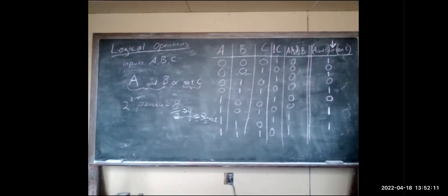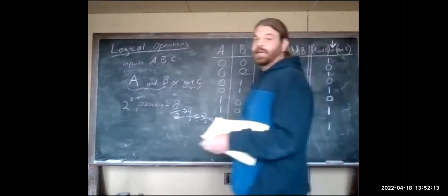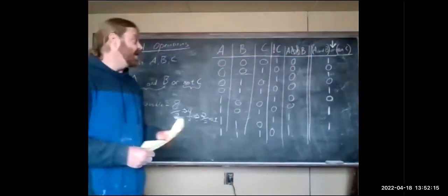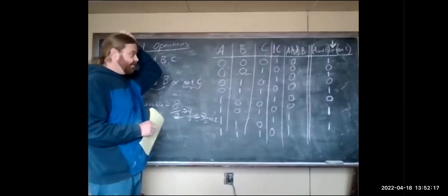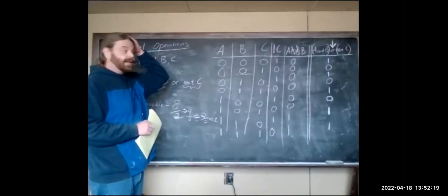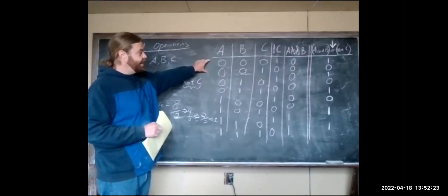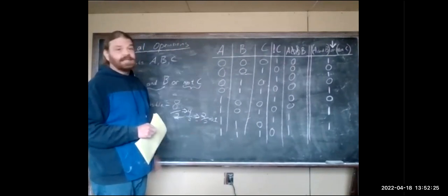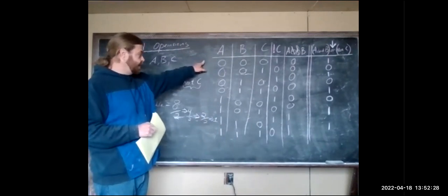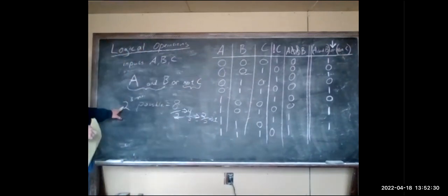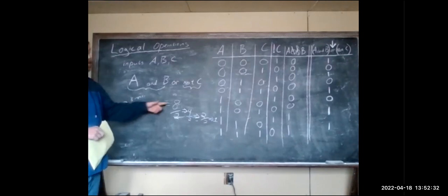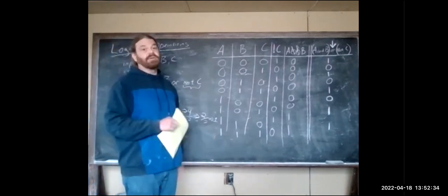So that's where we would use the truth tables. You can see the pattern, you could build straight up from that and get fairly large fairly quickly. Because every time we add another input, we have to do twice as many. If we had 4 inputs, there'd be 2 to the 4th possibilities, or 16 rows with 4 inputs.